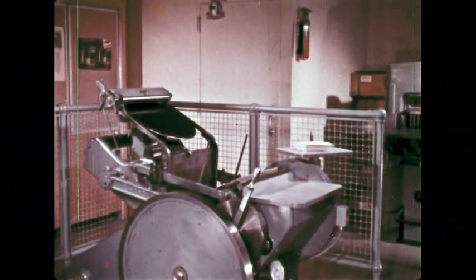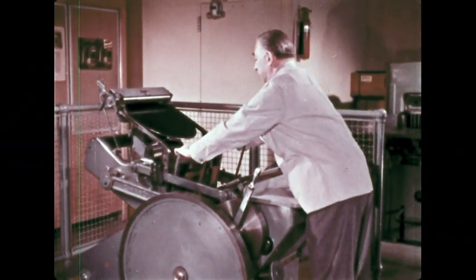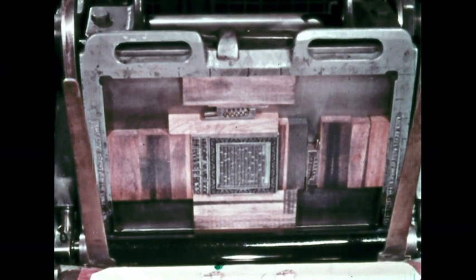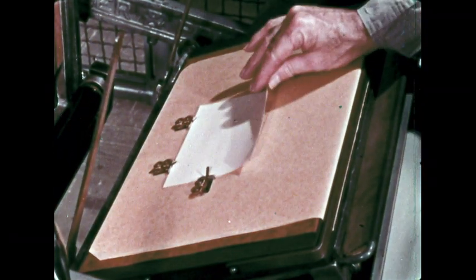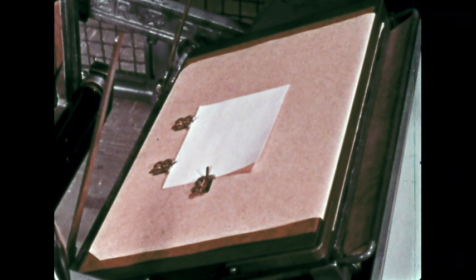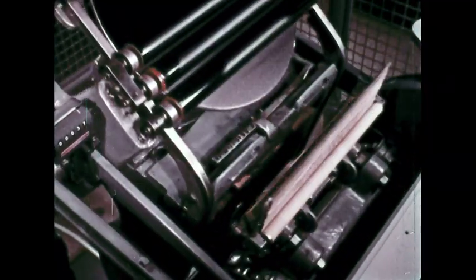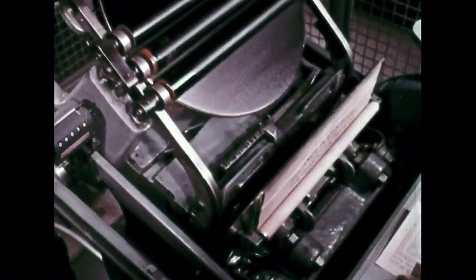The last element we require is the printing machine, or the press itself. There are several basic types of printing presses, and the simplest of these is the platen press, where the printing image carrier or form is held on a flat surface or bed, with the material on which the reproduction is to be made on another flat surface, usually called the platen. When the platen and the bed are brought together, the ink is transferred from the printing image to the material.